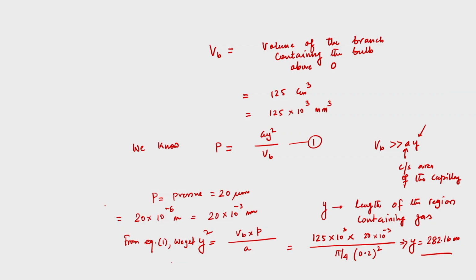That is the beauty of this kind of gauges, that if you would like to measure absolute pressure, we can. So, for the measurement of 20 micron absolute pressure, the gauge reading will be 82.16 millimeter. Now if we know the gauge reading, from there again we can calculate the absolute pressure, that is what we can measure using this kind of Macleod gauge.